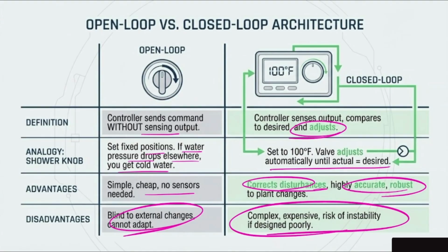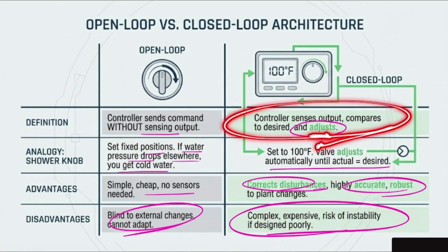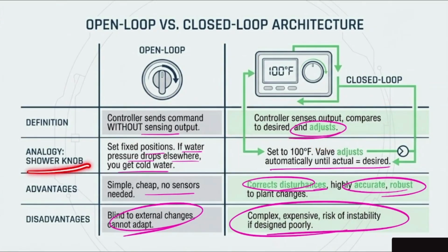But if you connect yourself, you're actually sensing. By sensing the output and comparing it to your target value, which means that it's suitable for your skin, you're actually adjusting it. So then we do have the analogy. You put the valve at a fixed position. If water pressure drops elsewhere, you get cold water.